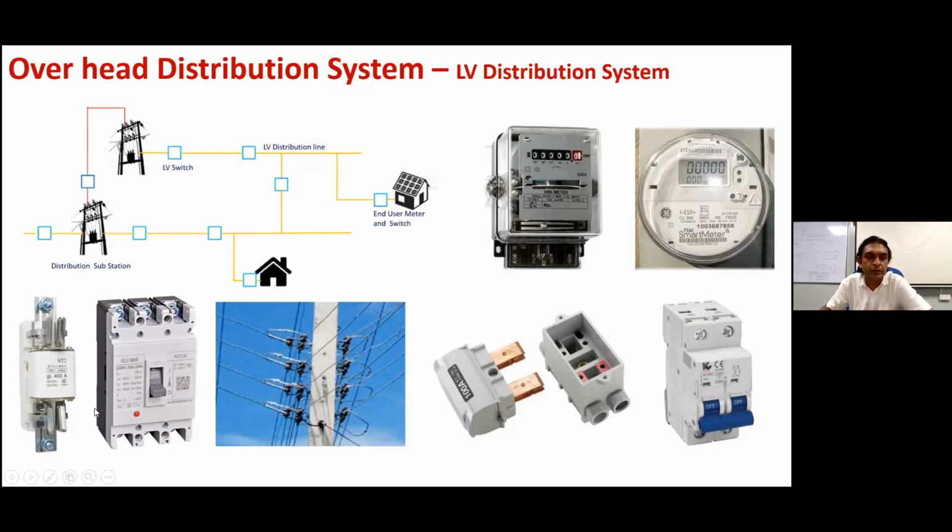Here also it's open, but if you use a fuse, when it's burned we have to remove it and install a new one. But if you use an MCCB, we can switch it on again using this lever. These two switches are installed very close to the transformer. Sometimes in spur lines, we use HRC fuses for protection, isolation for the fault in the spur line.